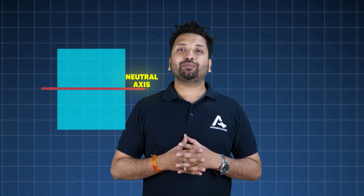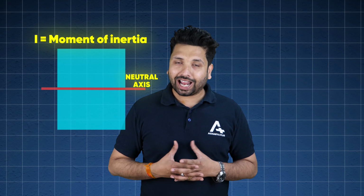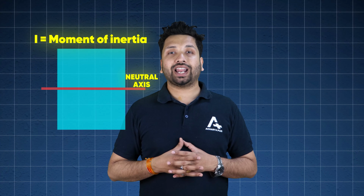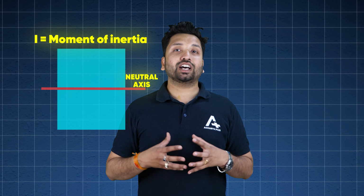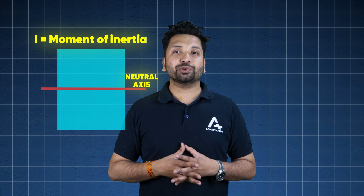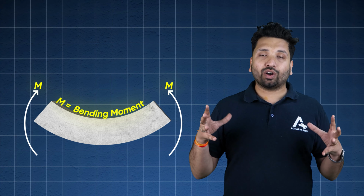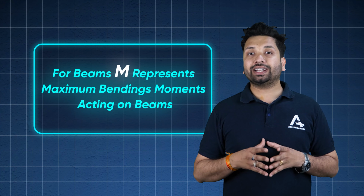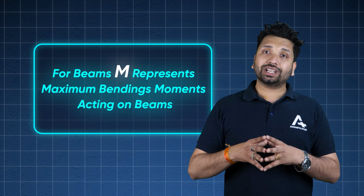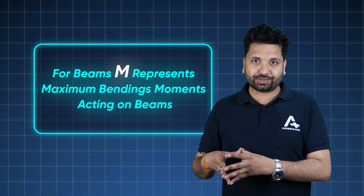The cross section will have a certain moment of inertia, which is also calculated with respect to the neutral axis. That is represented by I. So remember, I is the moment of inertia about the neutral axis. Now, the bending moment acting on the beam is represented by M, which is nothing but the maximum bending moment acting on the beam. Using this formula, you can calculate the maximum bending stress.